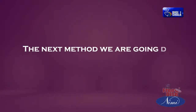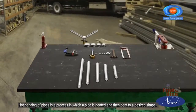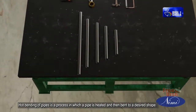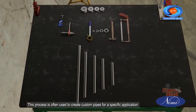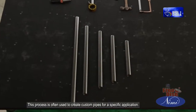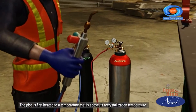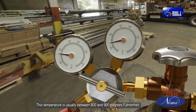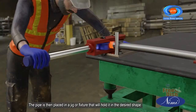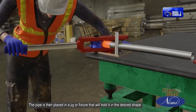The next method we are going to see is the hot bending method. Hot bending of pipes is a process in which a pipe is heated and then bent to a desired shape. This process is often used to create custom pipes for a specific application. The pipe is first heated to a temperature above its recrystallization temperature, usually between 800 and 900 degrees Fahrenheit. The pipe is then placed in a jig or fixture that will hold it in the desired shape.